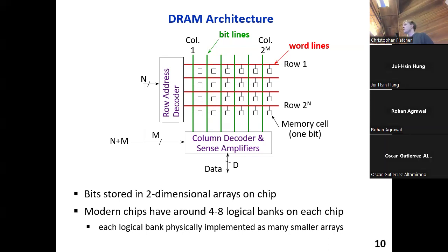On the other hand, if you don't have the row that you need in the row buffer, or, and this is the part that you can configure in your BIOS, under the DRAM section it says open page, closed page policy. The word page has nothing to do with virtual memory because, of course, these different communities didn't talk to one another and therefore call completely different concepts the exact same thing. So there's a way to actually turn your row buffer off. If you've turned your row buffer off, or if the row buffer is on but the data that you want is not in it, what you're going to have to do is read the data out, then merge the write that you want in, and then write it back.